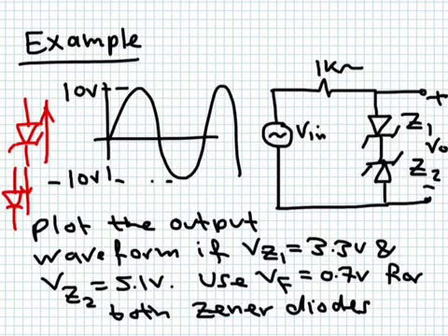So in this circuit, we have two zeners, Z1 and Z2. How can a current flow in this branch? Well, the branch containing the zener 1, Z1, and Z2. Well, there are two possibilities. This one can be forward biased, so this is a diode. It will allow current to go in this way, and this one is in breakdown region.